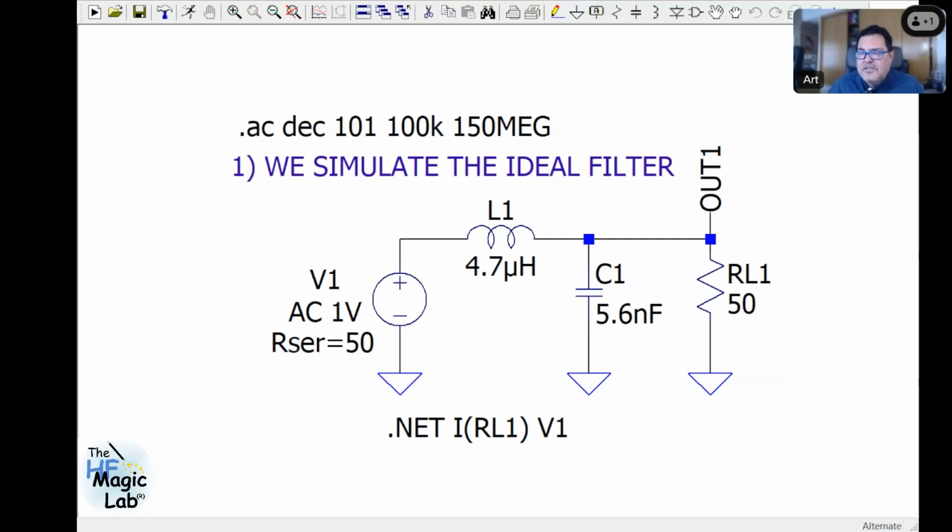Do you have resonances in the output impedance? And what happens at the other side, in the load? What we usually have is the line impedance stabilization network. If you are measuring differential mode emissions, probably you will use here 100 ohms instead of 50 ohms. Or if you are measuring common mode emissions, this impedance is 25 ohms in a typical LISN.